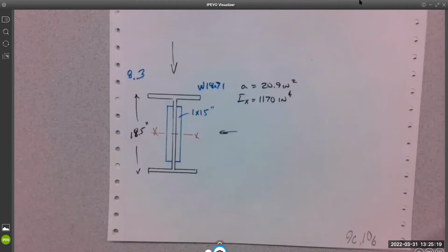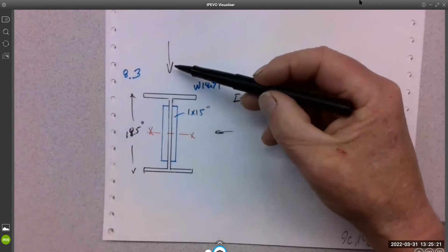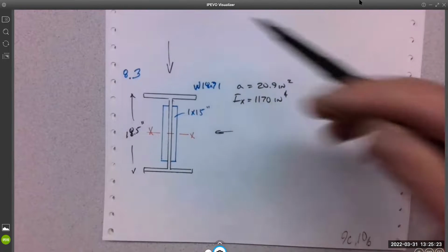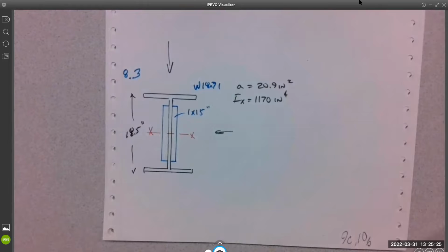Gravity's straight down though, that's this critter, right? Weight and gravity, the Earth's shaking. So even though it's not very common, we design for it big time. So things get massive because in this region, I believe we designed for a 7 earthquake, not a 9. That's why all the bridges will be gone if we get a 9. Nothing is designed for a 9.